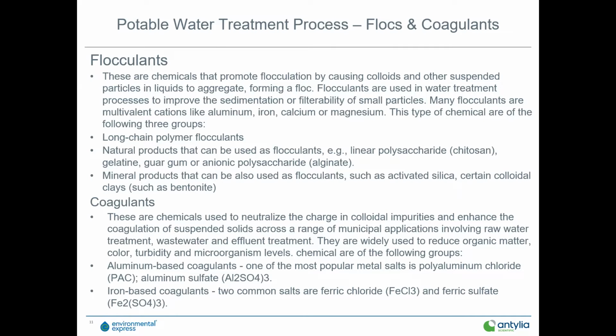Now, the whole value of either a flocculant or a coagulant is that they will aggregate smaller sediment and other particulates in the water into a flock. As this flock grows bigger and bigger, it will settle out to the bottom of the clarifying tank. This clarifies the water tremendously, as well as reduces some of the ionic contaminants in the water stream.